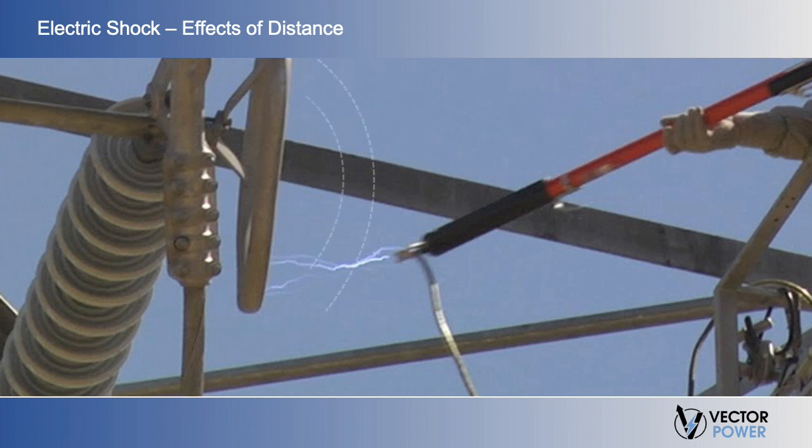Since these fields have a causal relationship with voltage, approach boundaries for safety have the same relationship. Higher voltages require greater distances for safety. Remember, you don't necessarily need to come in contact with those energized circuits or parts for them to arc across and give you a shock.